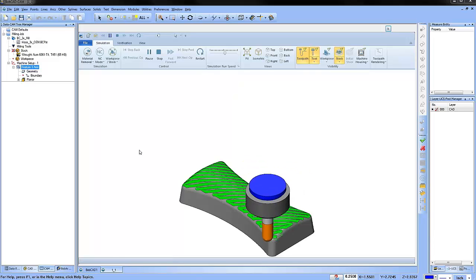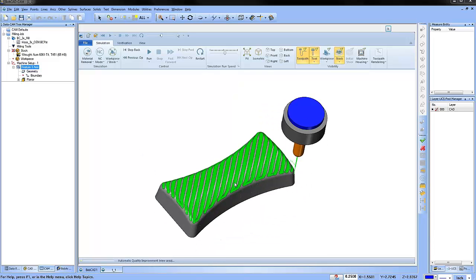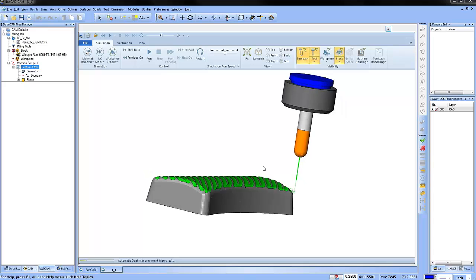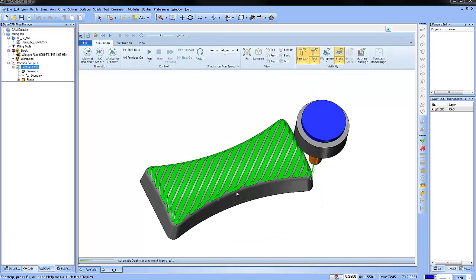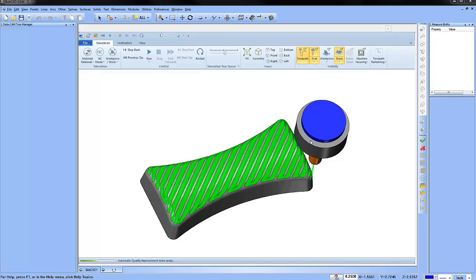and now we're able to see the toolpath is moving back and forth across the model. And when it does that, you can see we're cutting into the model, so we're getting this textured pattern, okay? Now, generally, a really common strategy is just to do two 45-degree paths intersecting with each other so you get a crisscross, okay? So let's look at how we would do that.